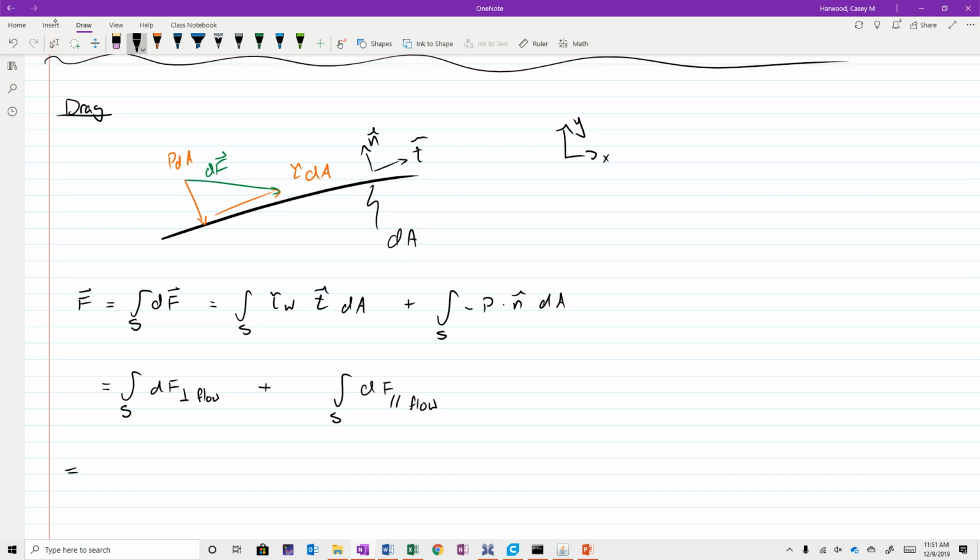And we named this integral of all the forces that occur perpendicular to the flow the lift, and the second one, with all the forces parallel to the direction of flow, the drag. Okay. In this case, we didn't make any assumptions, but we can assume that the flow is being defined by some uniform upstream flow direction. It's very rare, and I specified this last time, that we have the detailed information necessary to actually carry out this integral directly.